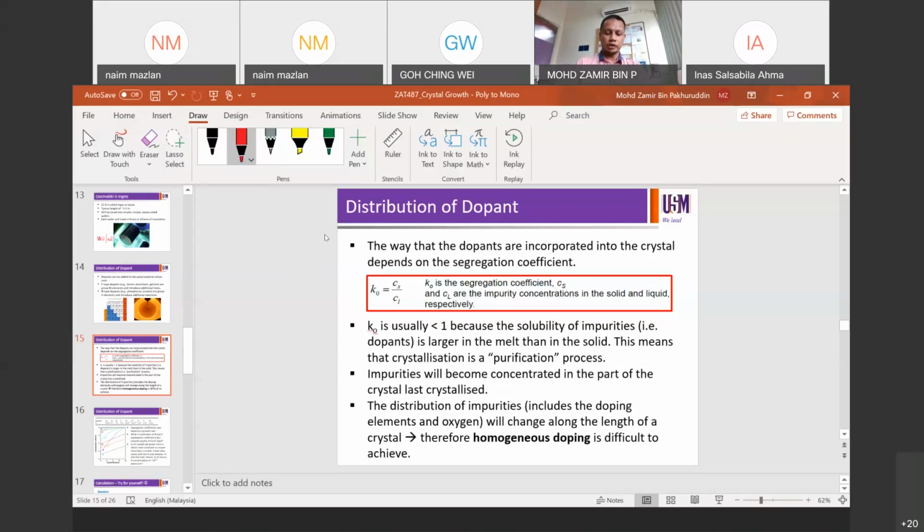This is happening to n-type because we'll see why later on. The dopant distribution is not so uniform, and then the manufacturers usually end up not being able to sell the whole ingot. So they grow like 2 meters, they probably can sell 1.8 meters, and another 0.2 meters needs to be remelted and then regrown into a new ingot. So you fabricate 100% of the ingot, then you can perhaps sell 70%, 80%, and the other 20% or 30% is lost, not sold.